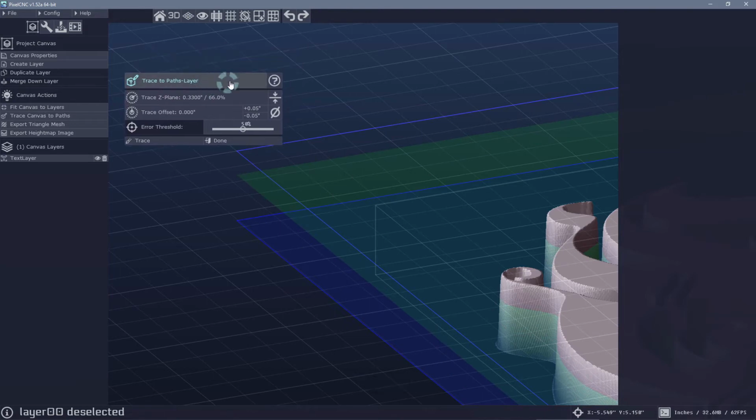And one cool trick is that if you hold down Shift while adjusting these knobs, anywhere in the interface, actually, it will magnify the change that is incurred by the mouse's forward and backward movement. And conversely, if you hold down the Control key, that will reduce the amount of motion. It will scale it down so that you can do more precise adjustments.